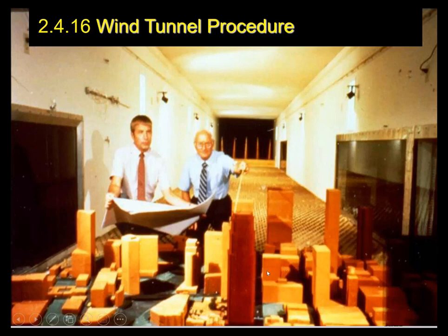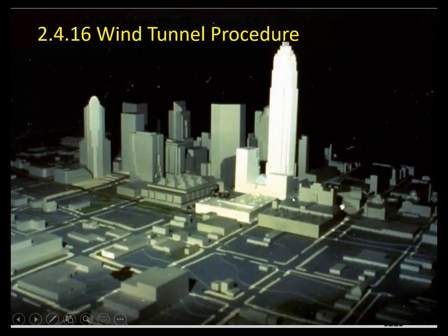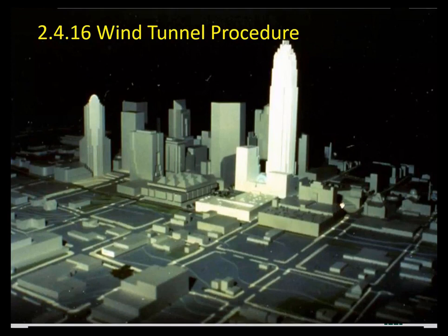What if a neighboring building were to disappear? What if this short building would one day be replaced by a tall building? You can play those scenarios in the wind tunnel. This is a Chicago building that was tested out. This is near the lake shore. Again, the same story. The building that is being designed in the wind tunnel is heavily instrumented. The neighboring buildings are not instrumented but modeled to scale.